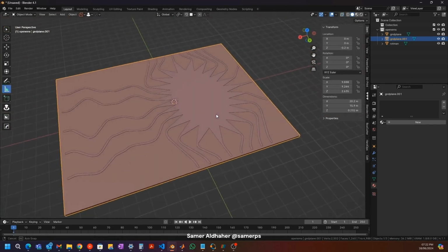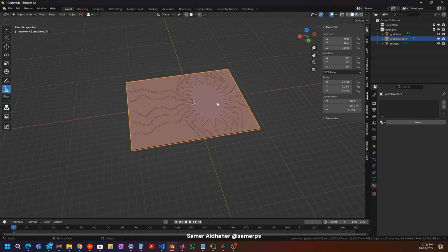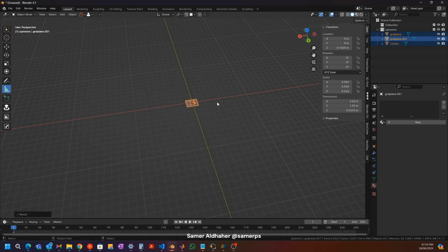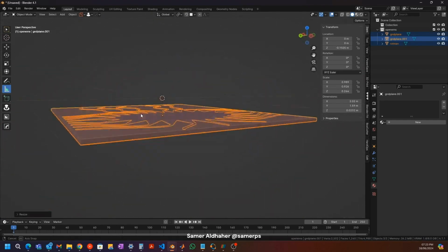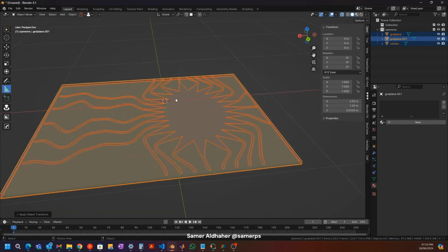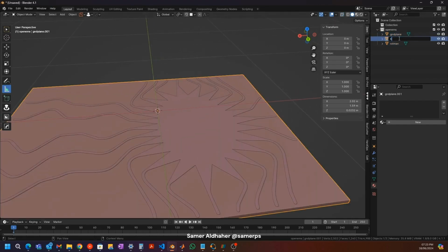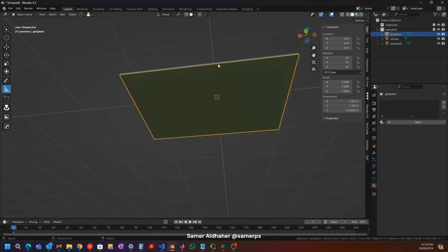Okay. In fact, the scale is too big for Blender. If you work with large dimensions, it can be difficult to navigate. So I'm just going to scale it back down, like so. All right, so that makes it easier. I'm going to apply all the scales and the transformations, and so now we have our substrate. There we go. And that's our ground plane.